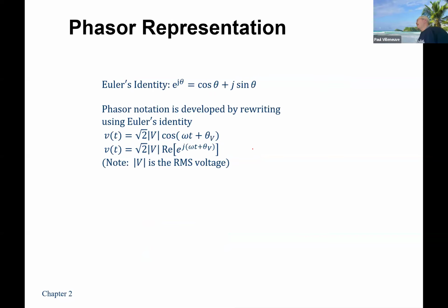So here's Euler's identity. Again, we went through that yesterday. Without a magnitude, well, there's a magnitude, it's just a magnitude of 1. So e to the j theta equals cosine theta plus j sine theta. If you haven't watched the lab yesterday, this is how you enter complex numbers with magnitude and angle in MATLAB. This is the only way that you can do it.